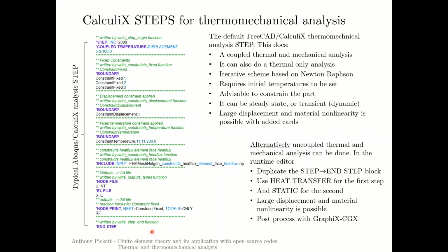In the second mechanical analysis, you could include large displacements, material nonlinearity. The problem of doing that, I will do it, but the problem of doing it is that FreeCAD cannot post-process the results. You have to use the special graphics processor from CalculiX, and I will be showing this. So as I say, I will show an example on how this works when we come to the analyses.